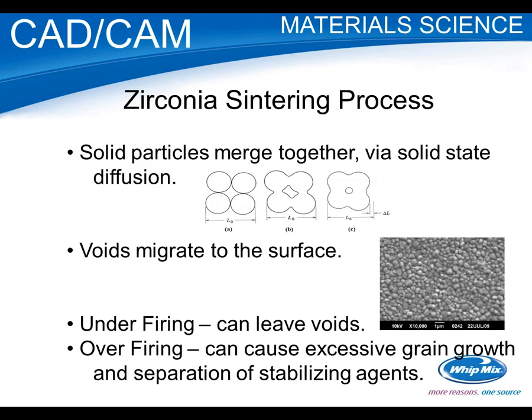If you're not getting the translucency you need, and there have been cases where we've gone through the sintering and we end up with a translucent grade that's a solid white chiclet, and it's like, whoa, what happened here? Well, it wasn't the firing, and it wasn't necessarily the zirconia. We had a contaminant in the process. So that's the other thing: as you're sintering, make sure you have a clean process, that your furnace is clean, and that you're not adding any contaminants.